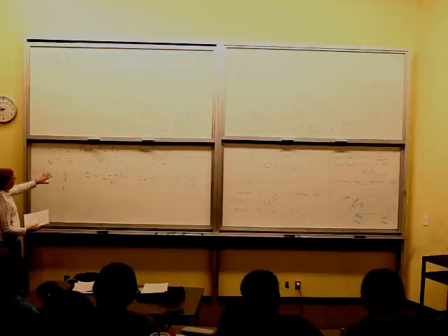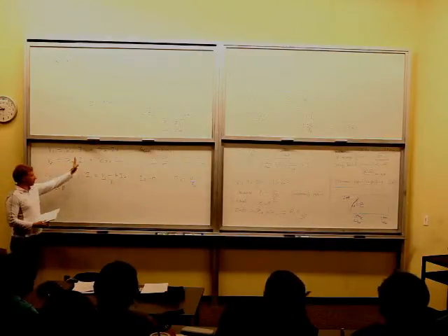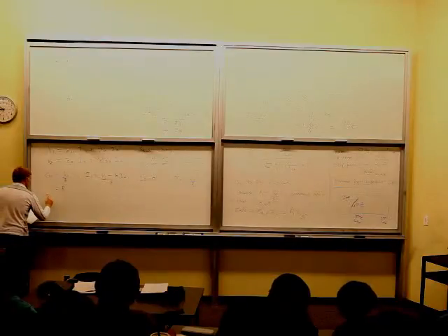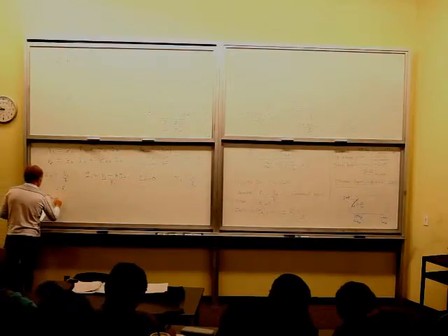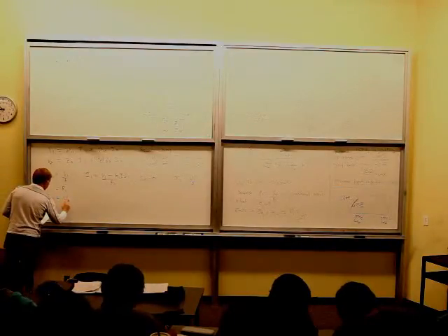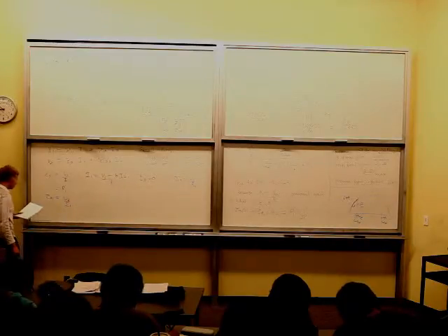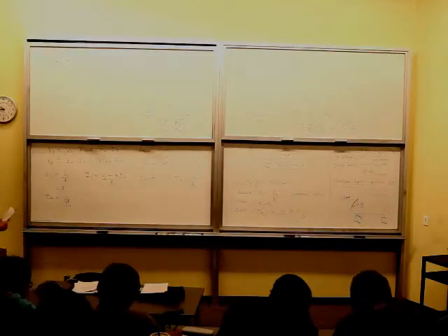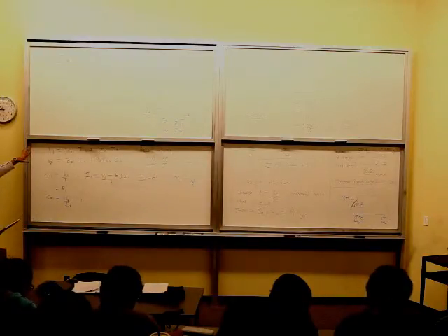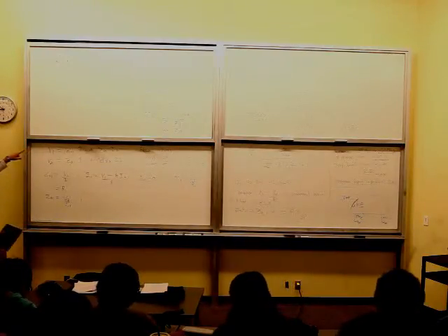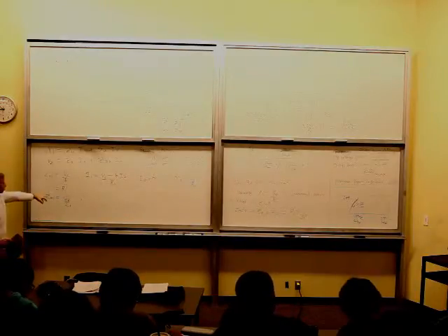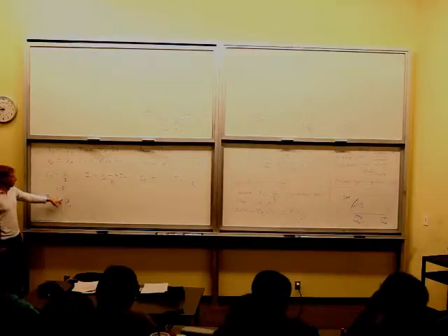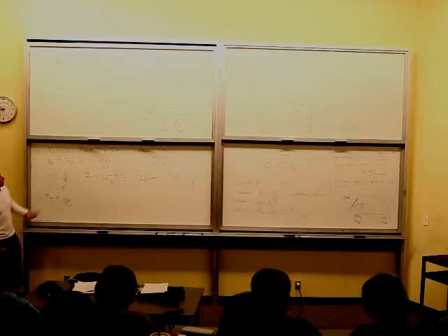Okay, now remember that I like to go to the next one here, Z21, because I already have I2 shut off. So let's write this out. Z21 equals V2 over I1 when I2 is off. And now the nice thing here is that that's pretty simple, right? So we can express V2 in terms of I1. Which we can do because we have a dependent current source now, the I1s are going to cancel, we'll be left with something.